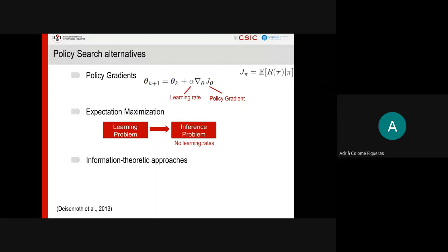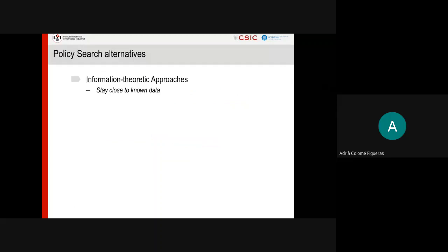One of the typical methods in this subfield is called relative entropy policy search. Imagine that the robot is generating samples of a task, and every sample is evaluated and has an associated reward. If the robot has performed a motion 20 times, and in 2 of those times the reward was very high, but the rest of the rewards were very low, what the robot would do, if we didn't pay attention to that, would be to just average those 2 very good samples and forget about the rest.